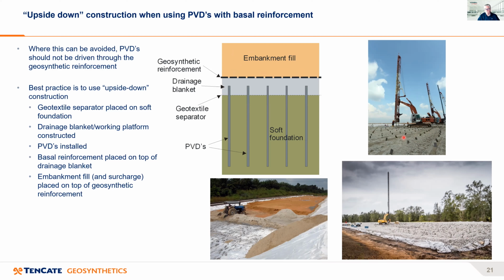But in some cases you'll find that you can't obtain sand, whether environmentally you're not allowed to use it, or it can be very difficult to obtain, or very expensive. And normally what can happen then is that you can use crushed gravels as the drainage blanket, as you can see in the bottom photograph here.